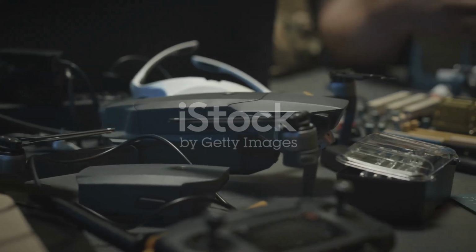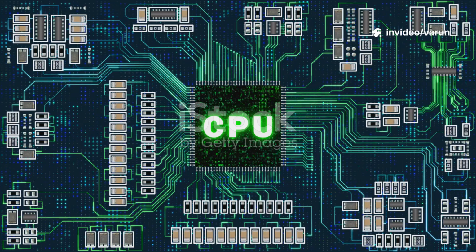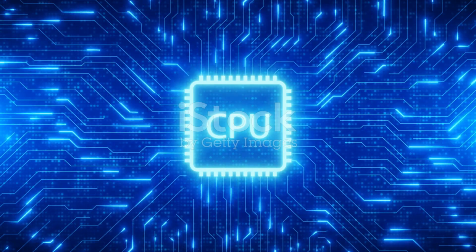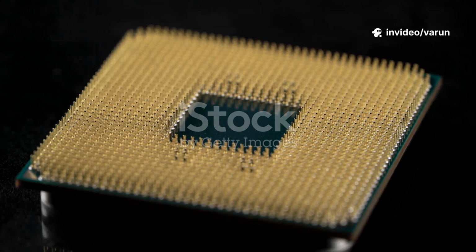Picture a workshop with a main workbench called the accumulator, a special register that holds the number you're working on. The instruction register holds the current command, and the program counter tracks which step you're on. Here's how the CPU processes instructions. First, the fetch cycle. The program counter points to the instruction in memory, and the CPU fetches it.